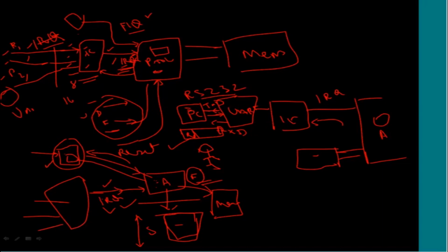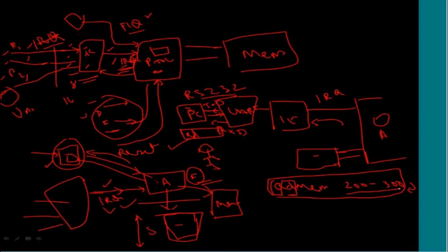Now we are sending a command, an ASCII command. It may say read mem, from 200 hyphen 300, assume in hexadecimal, and then a carriage return. So what happens when this command is given? The monitor which is running will wait for the complete command to be received from the PC. It will read one character at a time, the r, e, a, d, then mem, and when the carriage return is given, it will understand that the complete command is given, and then the processing takes place.